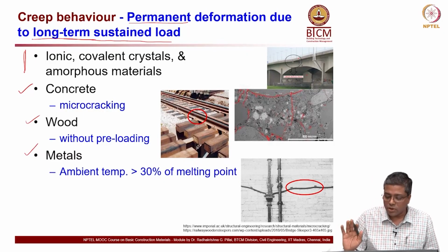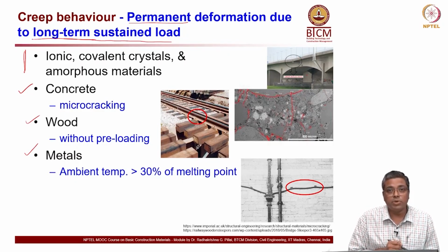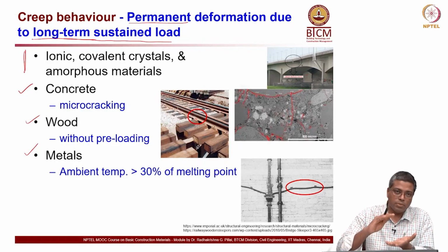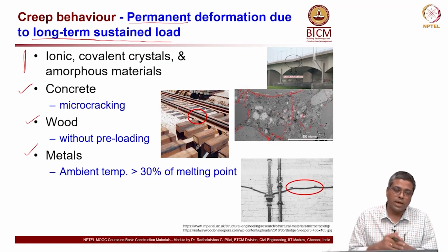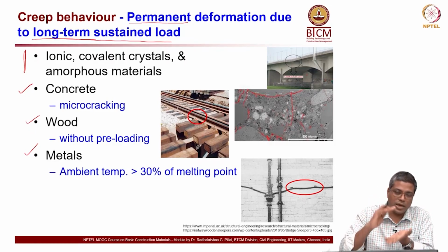And here we talk about flexural creep. Now, another example is wooden sleepers below the railway tracks. You can see here the wood. Imagine you have a particular thickness, and if that wooden piece is used without any pre-compression or pre-loading, then maybe after the rail tracks are placed and the train starts moving, you will see more deformation, or the wood gets compressed by, let us say, a thickness of delta x.